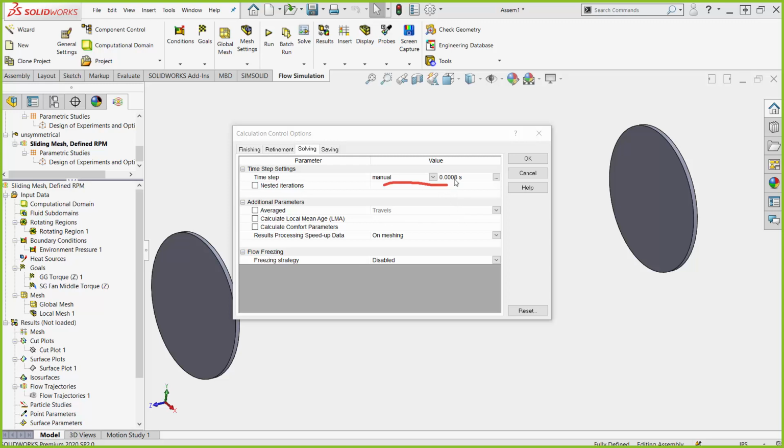My time step is based on having a total output of 100 steps. That seems to be enough of a refinement to capture the flow correctly. Be aware I'm adding in error because now I am forcing it to make time steps potentially larger than actual perturbations in the flow.